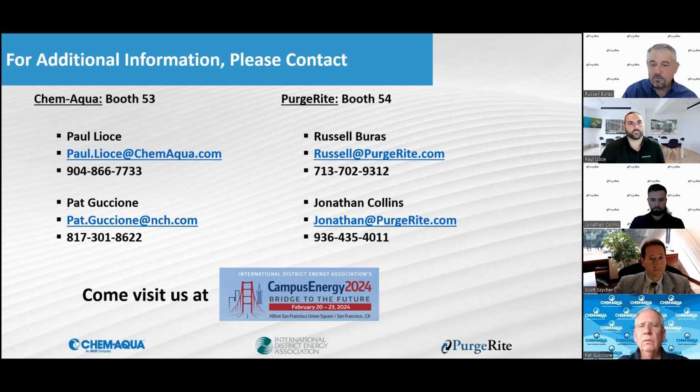Now, if you walk away from that, or if it's tied to carbon steel components, that's when you need to introduce the chemistry part, either laying it up or circulating it through that volume of water that's going to ultimately go into the steel, because you've got to be able to inhibit that. Poly doesn't really care, but you've got to have it in the carbon steel. Do you concur with that, Paul?